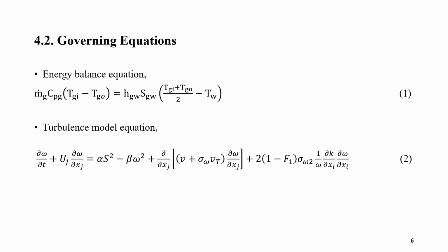Now, in terms of the turbulence model equation, we are using the SST k-omega model, which has been used to simulate the near wall region more accurately. As we are simulating the entire model of the exhaust manifold, it is mandatory to know the near wall region temperature.